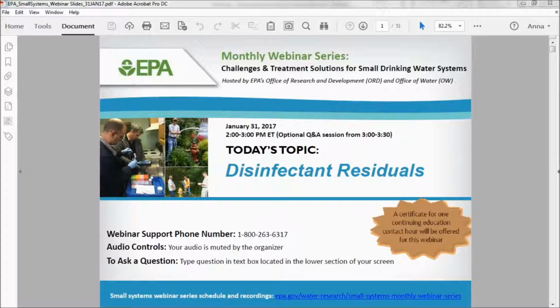Well, according to the manufacturer, an alkalinity above 250 milligrams per liter can result in not having full color development, or it can cause an artificially low chlorine residual result. High pH, I would say once you're up to around 10 or 11, that's when you might have some concerns.